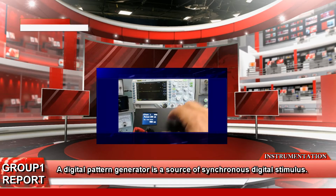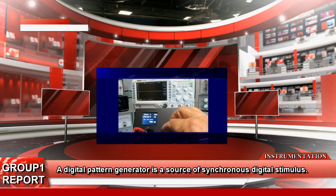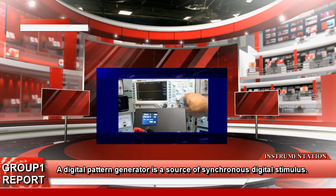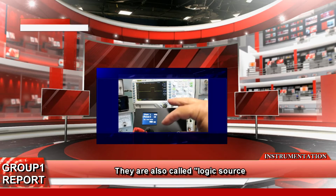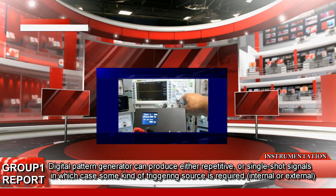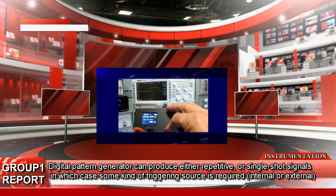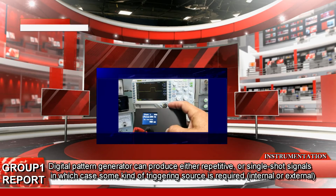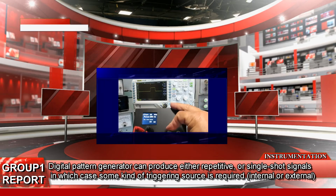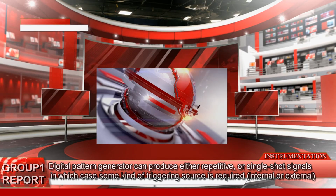A digital pattern generator is a source of synchronous digital stimulus. The generated signal is interesting for testing digital electronics at logic levels. This is why they are also called logic sources. Digital pattern generators can produce either repetitive or single-shot signals, in which case some kind of triggering source is required, internal or external. Digital pattern generators are today available as standalone units, add-on hardware modules for other equipment such as a logic analyzer, or as PC-based equipment.